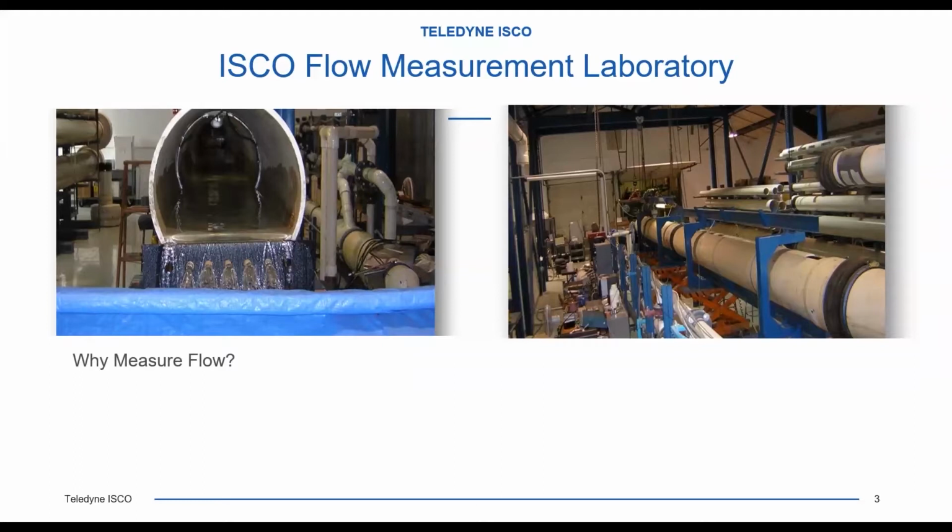So why do we measure flow? A lot of different reasons, but some of the most common: inflow and infiltration, or I&I studies. And if you're from Europe, they are considered flow surveys a lot of times. Enforcement requirements, industrial pretreatment. So they're billing people out there for what they discharge, and they need to measure that flow so they can get an accurate bill. And then finally, hydraulic modeling is another big one in the collection system. And they're using the flow data to help them tweak and improve their hydraulic model.